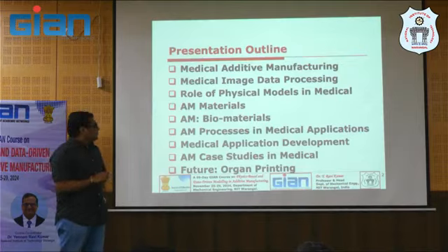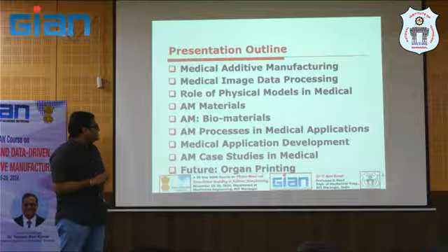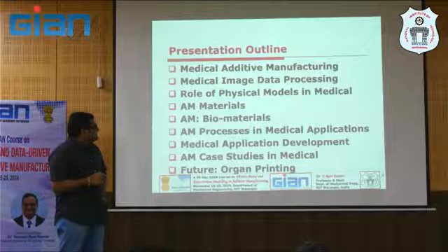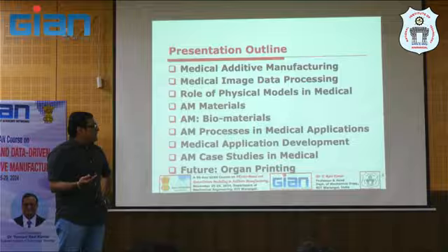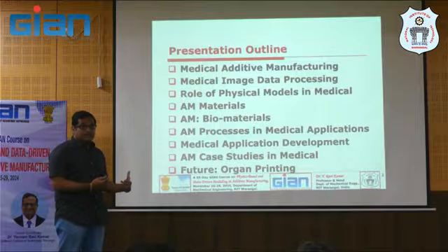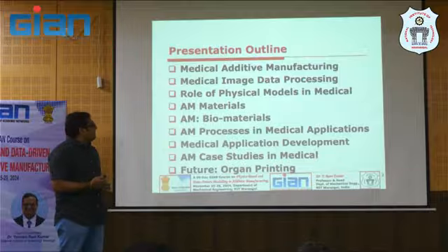So then we are going to use medical image processing for that. And once you have done that medical image processing of the images, then we can save it there itself as an STL file. So basically we need to have an STL file to 3D print it or to additively manufacture your model. In this case it is a bio model, which has been acquired from the patient data.